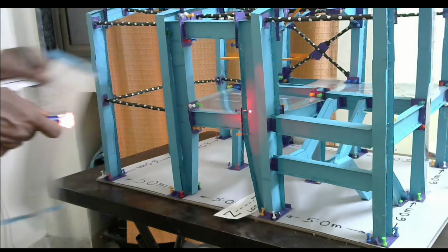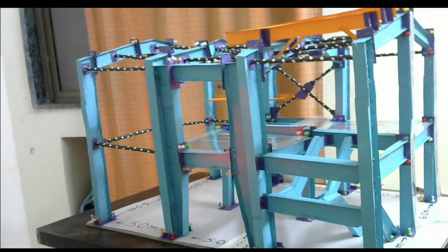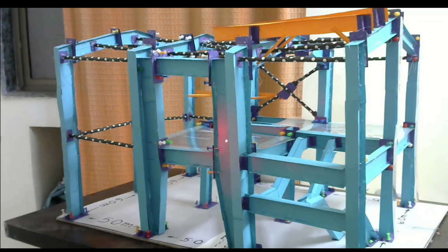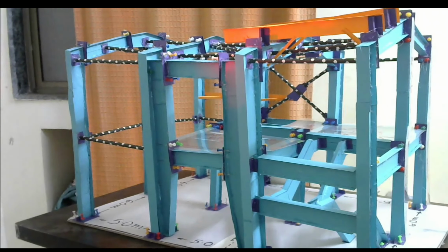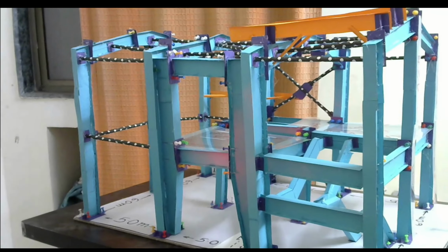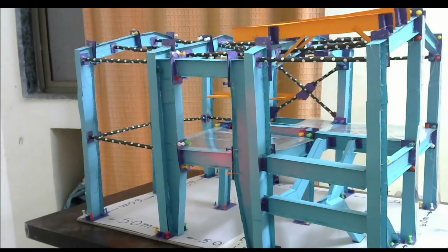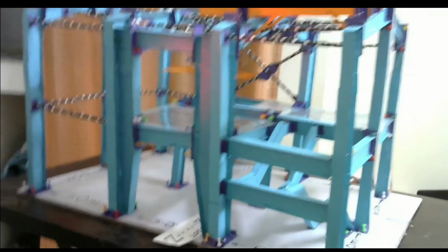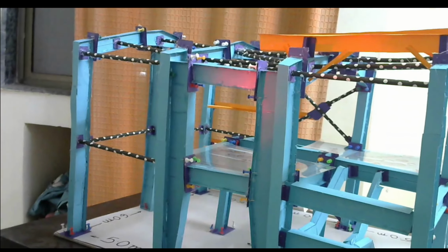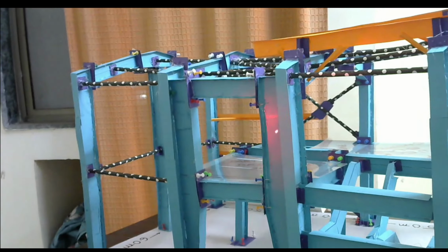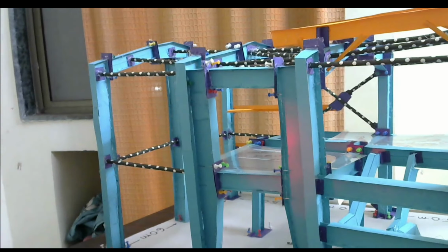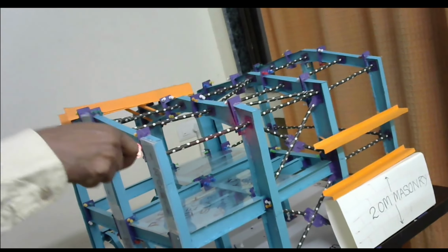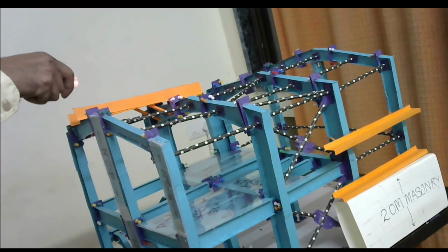Now if we come to the top part of this portal frame, LX is again 3 meter, LI with the same consideration as below, LI is 3 meter. LZ: fixed at top, fixed at bottom, but sway frame. For a sway frame with fixed at top and fixed at bottom, the effective length factor is 1.2, so the effective length becomes 3.6 meters. Almost the same is the case for this portal frame as well. So this portal frame and this portal frame will have similar parameters.